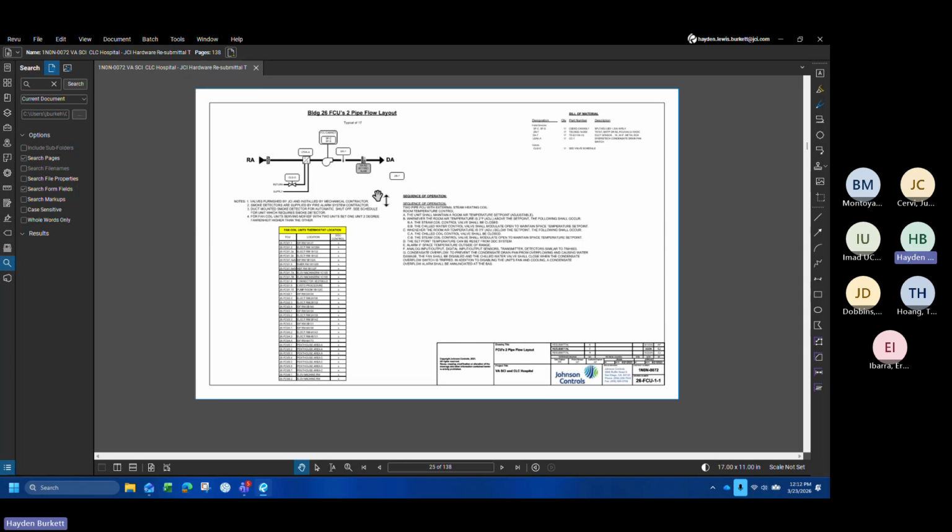As far as all that information I was just talking about, that strictly applies to the air handling units. We don't have any sort of entering and leaving temperatures to these fan coils. Would kind of be nice, but what we're running into here is a limitation of the equipment to actually provide something like that. So it also was never called for this equipment to have that. So just a little bit of a heads up. The air handlers will have that entering and leaving temperature, but the fan coils will not.